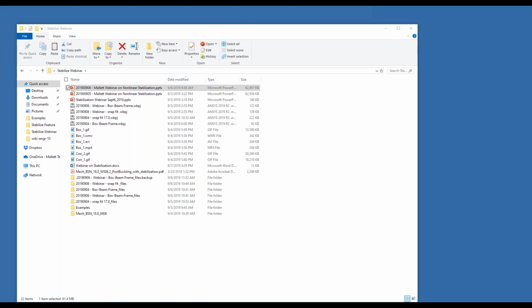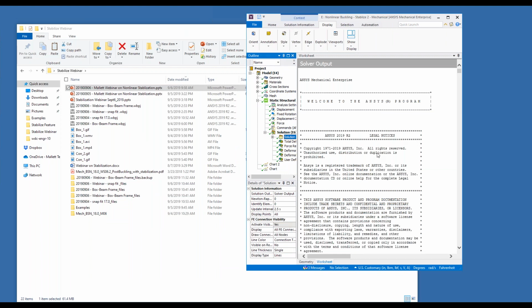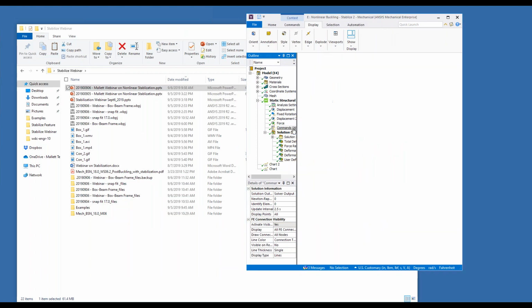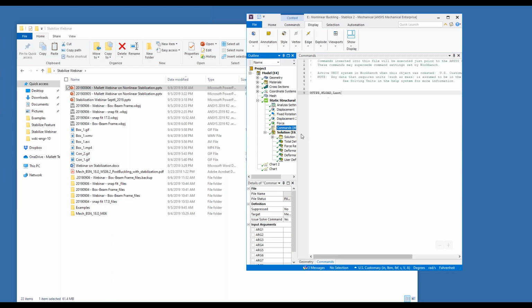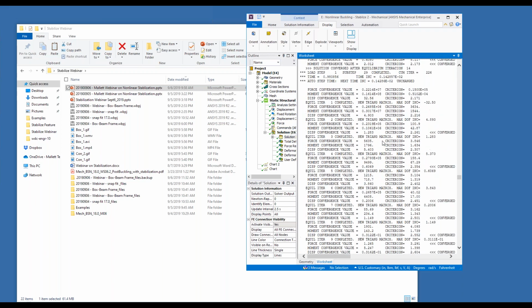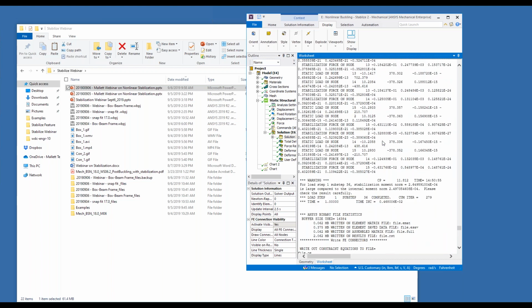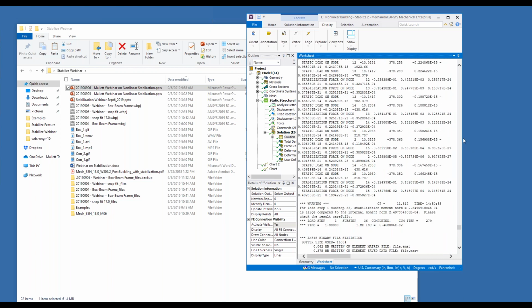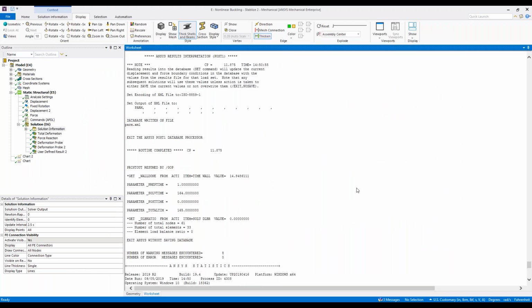It is actually a good question because this is important. You really want to know how much energy is applied. So I'll keep the screen. This one had the command in it. You see the command here is active, and I solved this problem. This is the command, and it will show you the following in the output. This is very important. Many young users probably don't know that. Look at the output, and you see a list of forces that are applied artificially to stabilize the problem. And it's really important that we actually compare.